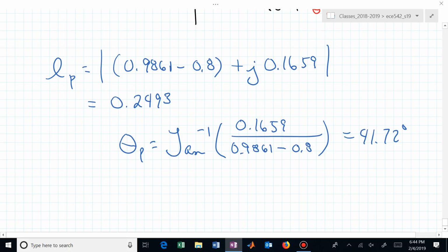So it's really just how do you want to approximate that derivative? And we did it with a first order approximation or a forward-looking approximation, and we'll look at other ways of approximating derivatives or integrals later in the class. We'll look at other ways of doing discrete equivalence. So the error is somewhat based on the sample period capital T, but it's also how we looked at it. We said this is now a forward-looking approximation to our derivative. So we'll look at other ways of going between continuous time and discrete time later in the semester.